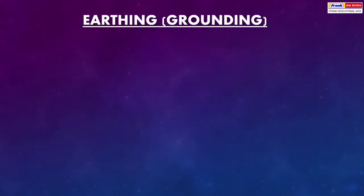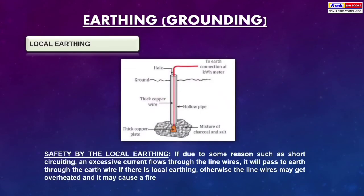Earthing, grounding, local earthing, safety by the local earthing. If, due to some reason such as short circuiting, an excessive current flows through the line wire, it will pass to earth through the earth wire if there is local earthing. Otherwise, the line wires may get overheated and it may cause fire.